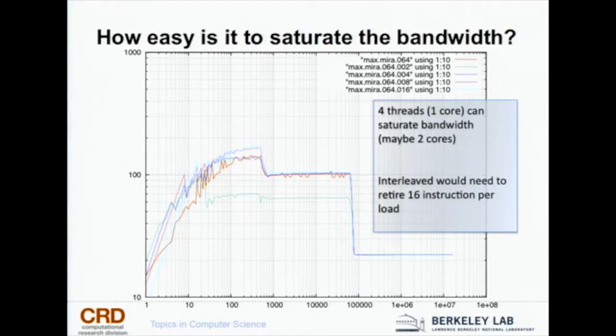So we're already at machines now installed in production where we really need to rethink and reconsider, maybe 2 of the cores here really should have been pulling compressed data out of the DRAM in the L2 and loading up uncompressed data into L1, or loading up uncompressed data into the registers. So there's a question of how you implement this, but I think the technology already exists. I have a similar calculation for Ivy Bridge.